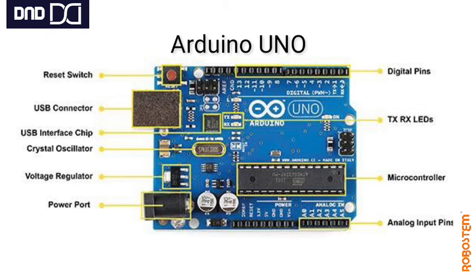The USB connector we use to power the board as well as to upload the program to the board, the program that we use to program the microcontroller. Then the reset switch. This reset switch we use to reset the program and not to erase it, so keep that in mind. When we press this, the program which is executing in between can be made to start from the beginning. That is what the reset switch does.